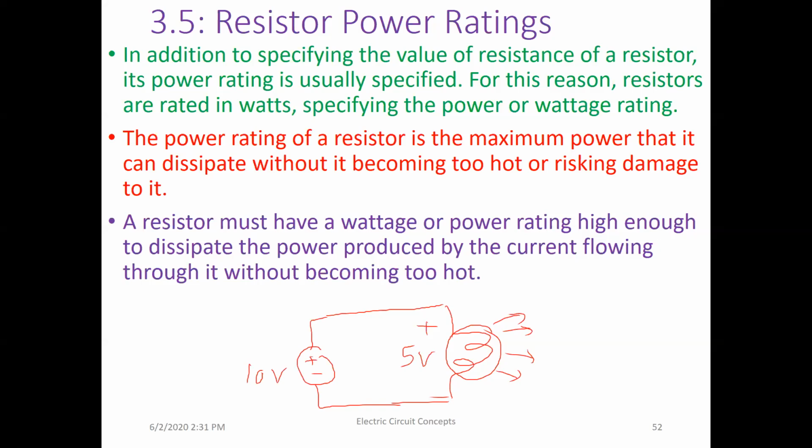So what do I need? I need to insert or add a resistor in this section here. I will draw the resistance. So I'm going to take off this line and then add a resistor here. That resistance R has a specific value, and I have to design the value of the resistance depending on how much current flows and how much voltage is required across the resistance.